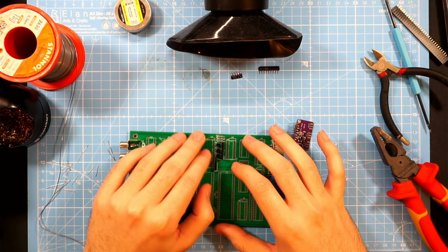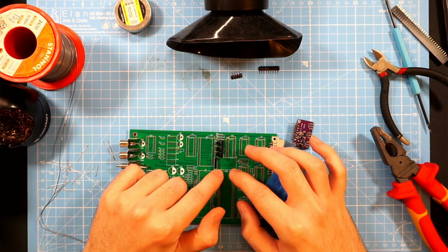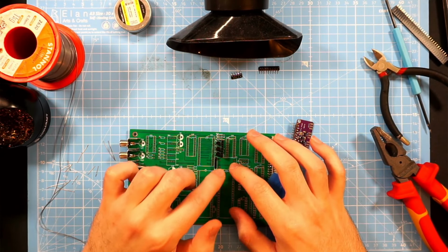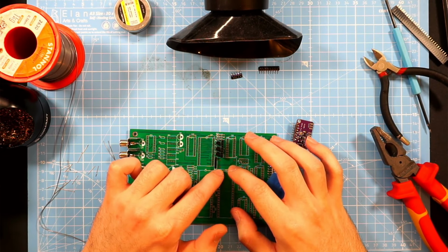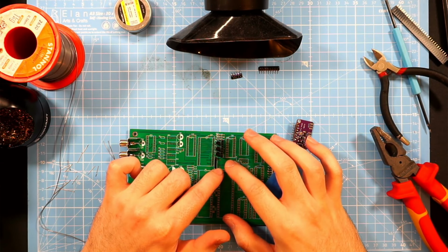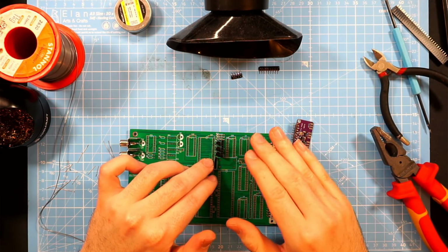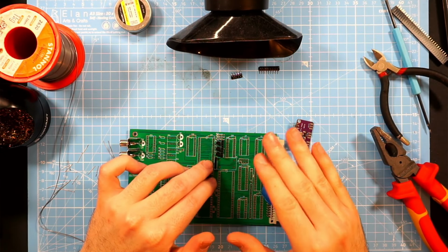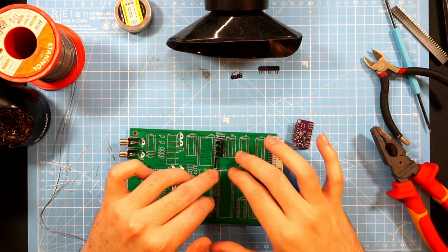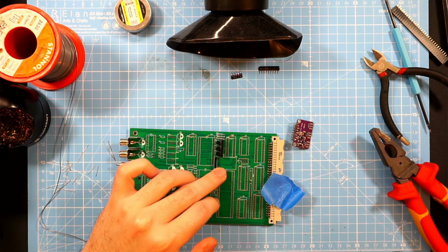Okay, I just found out that I don't have a 1 megahertz crystal. Not too much of an issue. I will add a socket instead and test with a 4 megahertz crystal. I just have to be aware that I would expect a fourth of the actual frequency that will be displayed later on. This means it will probably... Yeah, I don't want to do the math right now.